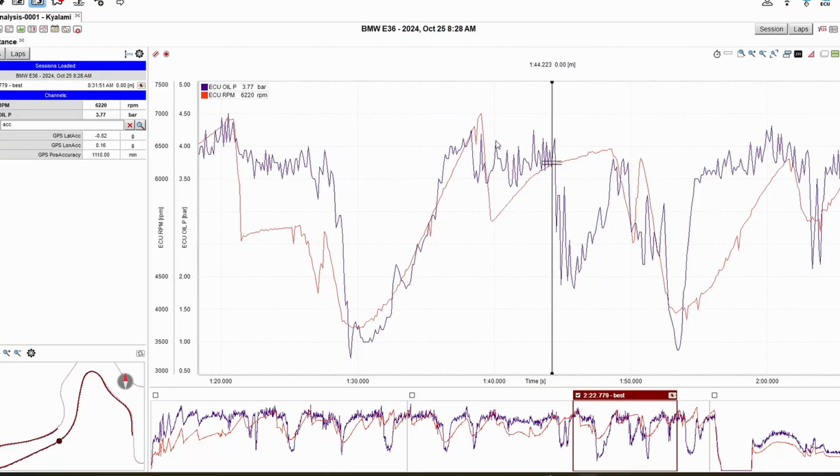And then something very interesting stood out for me. So what I saw here, I'm not sure if you can see it. It's happening here on the brakes, and it's happening here through the corner. Can you see it as well? What is happening is we're going from 4 bar pressure to 2 bar to 1.8, like that. And we're talking about the time of, it's like a second.